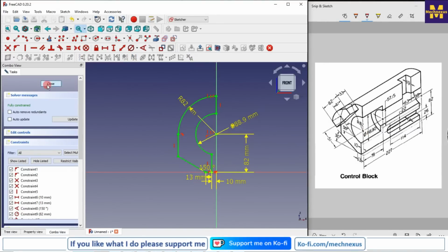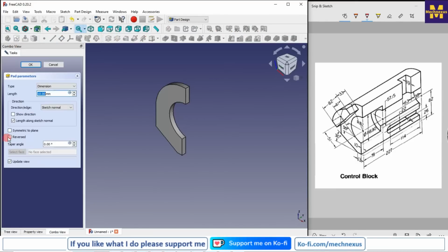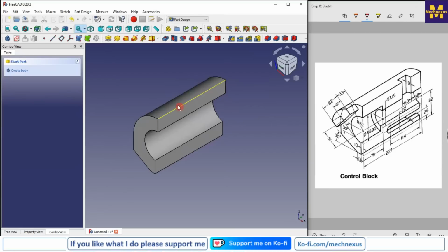Now we will come out of the sketch and make an extrude of 227. Here I will reverse the direction and give 227. So here is our base profile.